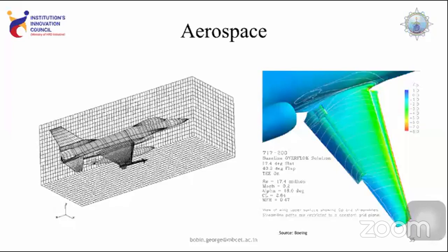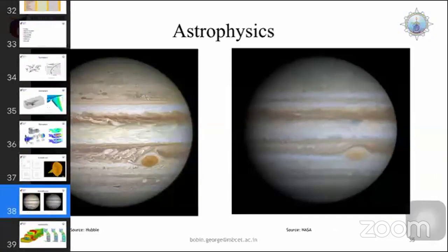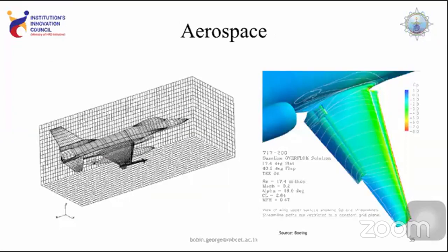Yeah, we were discussing mainly about the wing generation, or the amount of pressure that we applied on a wing. Whenever you have a fully developed flow over an aircraft wing, the basic model of turbulence that we apply is K-omega or K-epsilon, considering at what velocity the flight is going to fly, as well as the Mach number of the flow, so that the flow can be considered a compressible flow or incompressible flow according to the flight. And according to the model that we have in flow, we can again go for what is termed the large eddy simulations or the direct numerical simulation we have.